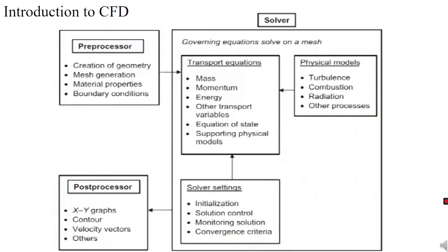Ensure the geometry is watertight and closed to prevent leakage between the solid and fluid domain, right? And the geometry must be continuous to avoid flow irregularities, especially for aerodynamic shapes like aerofoils or turbine blades. Then we will go for the meshing, but before that, we need to define the computational domain. The computational domain is based on the problem type, whether it is external flow or internal flow. So we need to choose various topologies, rectangular or circular domain, depending on the flow scenario.